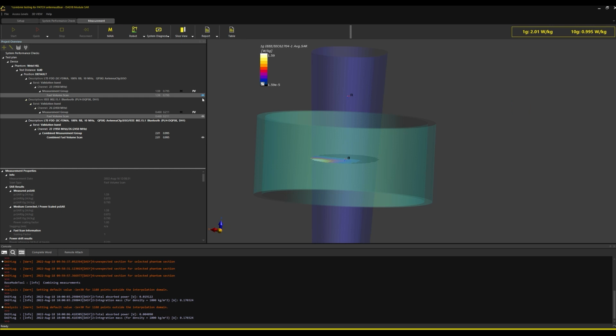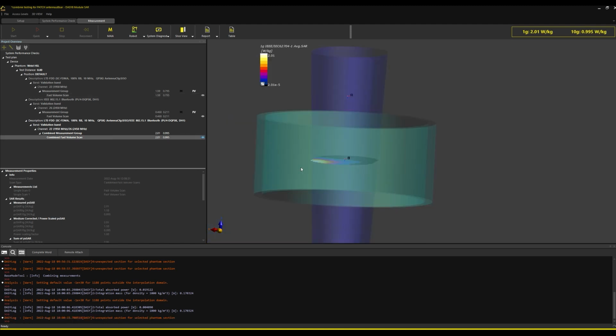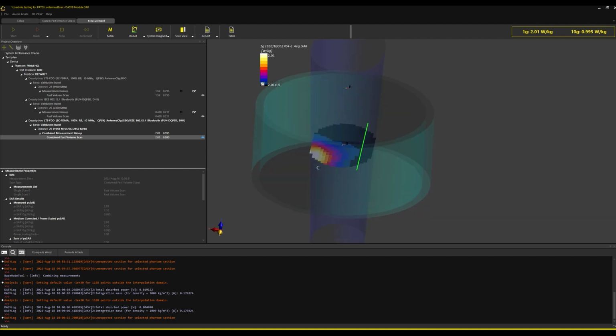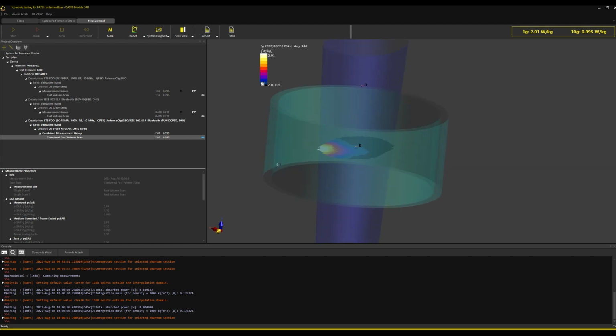The combined SAR plot is post-processed by evaluating the point SAR for each individual distribution on a fine grid and then adding the SAR values to produce the overall plot. Multi-TX SAR evaluation can be similarly evaluated for all the other special phantoms such as the headstand, face down, SAM chin and ankle phantoms.